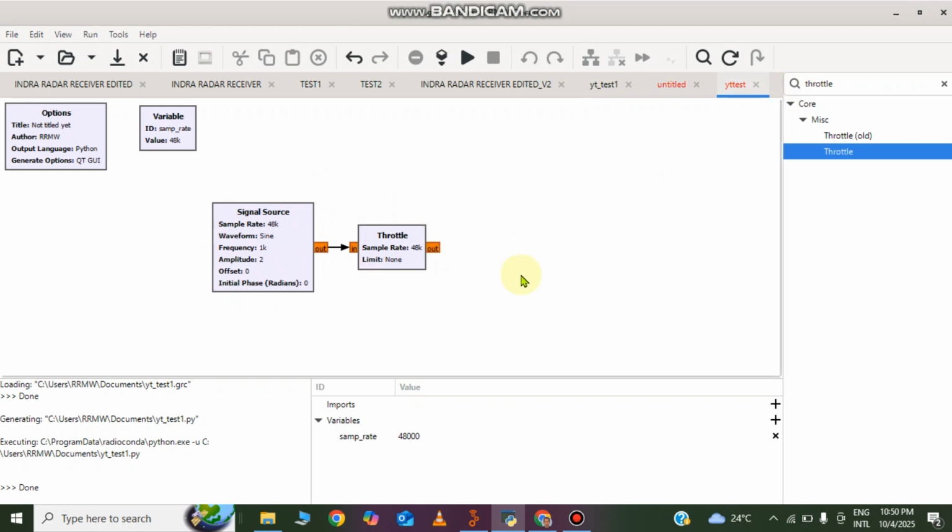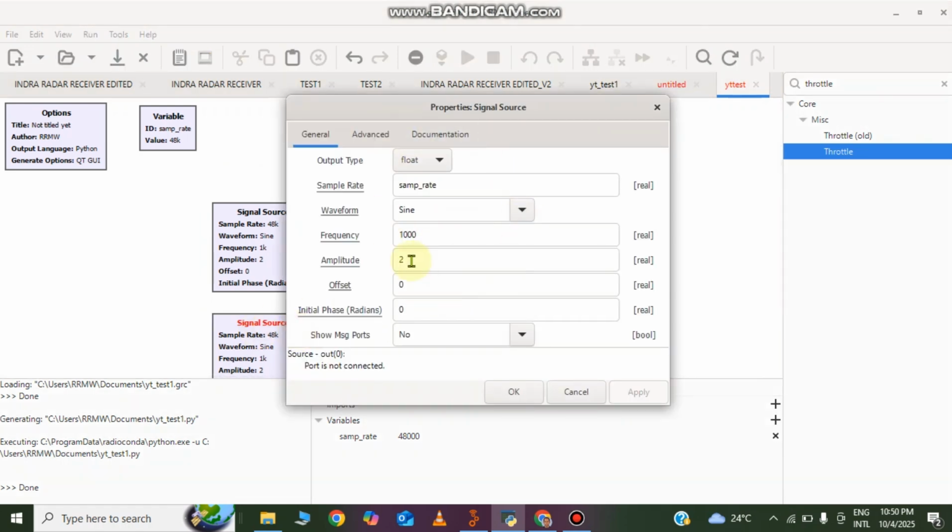then I'm going to introduce another signal source. I can get that block from here also, but I prefer to copy this source and reuse it. In order to copy, you just click in here, press Ctrl C from your keyboard, and then click in here and Ctrl V. You can click and drag the new block, and I'm going to change the details in here.